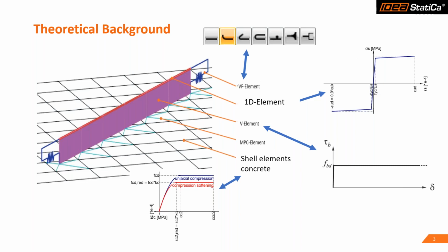In these shear field elements, we can calculate stresses. What does this mean? It means that if you have the bond stresses, you can investigate the required anchoring length, which is very important. You can see that all the physical non-linearities are taken into account, but also different types of anchoring. If you have hooks or other types of anchoring, you can include them in the model, and they are taken into account as springs. If you ask now, springs, it means stiffness, where this stiffness comes from. It comes from the recognized literature and, of course, from experiments.